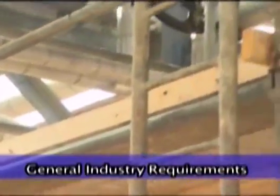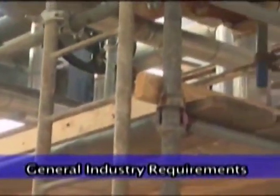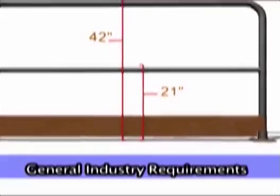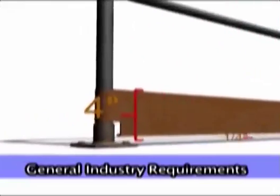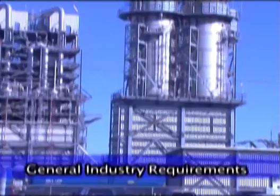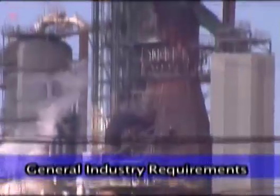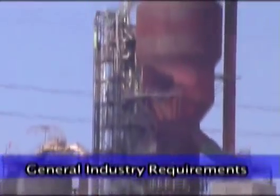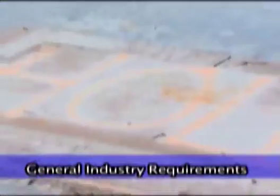Wherever there is the risk of tools, machine parts, or equipment falling to a lower level, toe boards must be provided. Toe boards should be 4 inches high, with no more than 1/4 inch clearance above the floor. Regardless of height, all open-sided floors, walkways, platforms, and/or runways above or adjacent to dangerous equipment must be guarded with a standard railing and toe board.